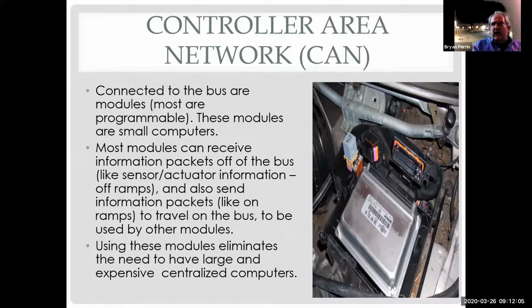And how they're integrated. And that's why it's really important that when we change modules, it's the right module with the correct software. Going to the junkyard and plugging another module in, the system may not work or the network may not work properly, and we may have some real unexpected differences. Also, if the part number, even though the module looks identical and has the same number of pins, is different, don't plug it in.